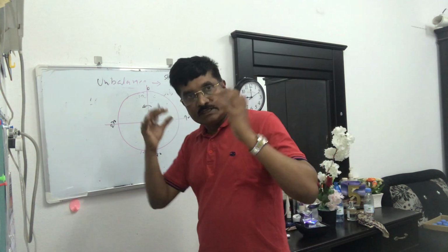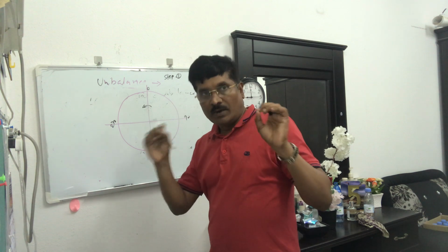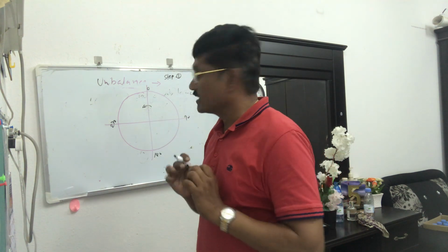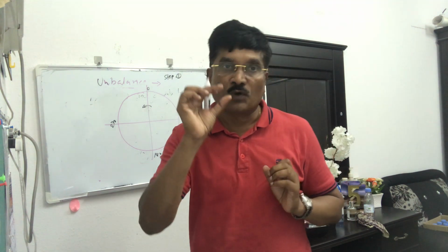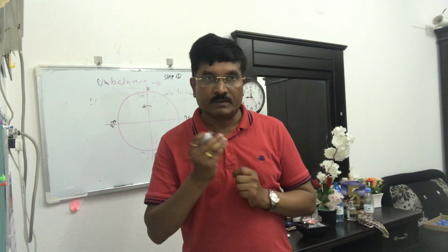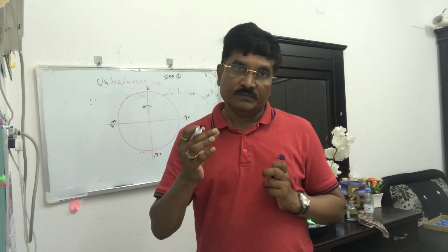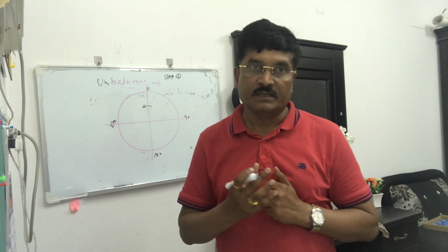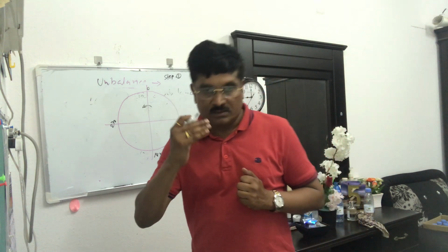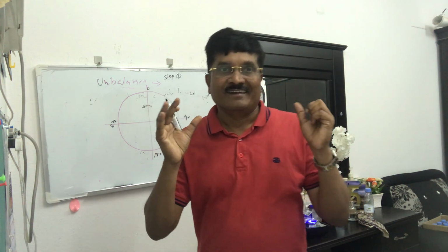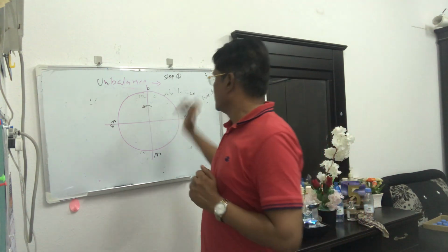So check at what location we can add the weight, mark all the degrees, check the safety provisions, then be ready with small weights that we have to add, from say 0.05 gram up to 5 gram, like 0.1 gram, 0.2, 1.5, 0.5. Keep all the weights ready so that it is easy to balance the rotor. This is our step 1.